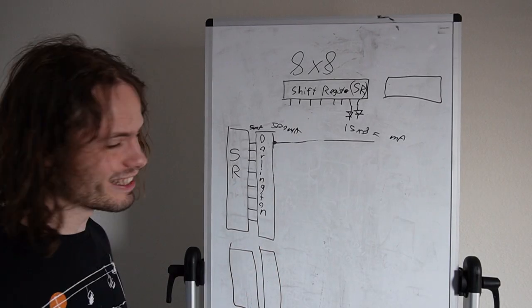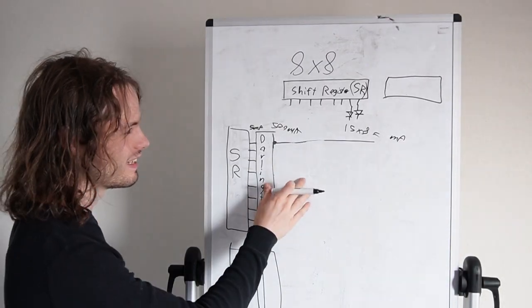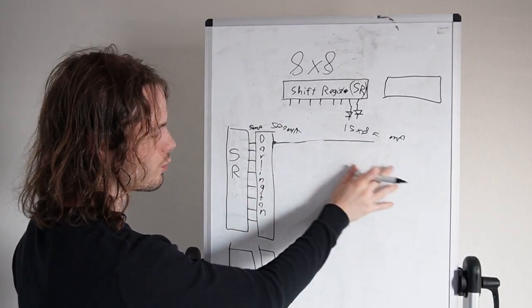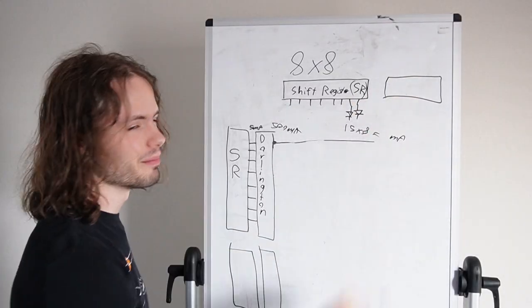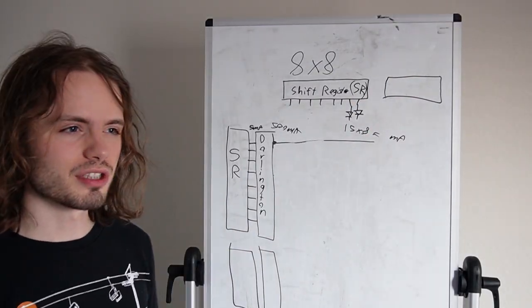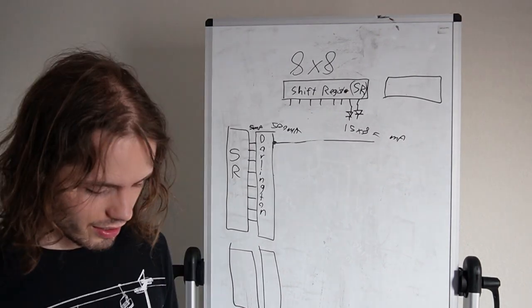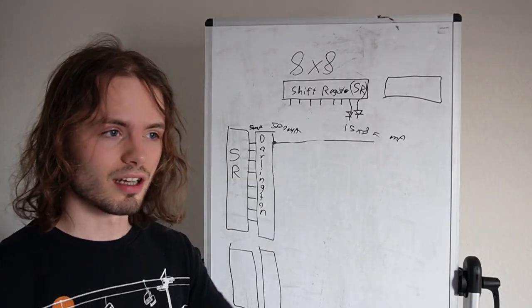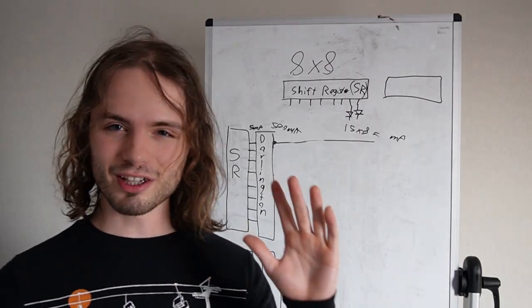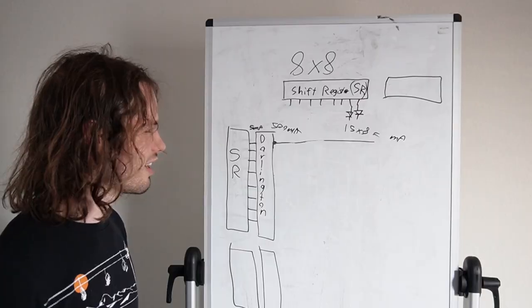The only issue is that once you start adding more columns, the Darlington here might not be able to handle the extra current, but that's for another point, and I think there's still a way to probably get around that. Maybe it's just another Darlington array or something where you put them in parallel, but anyways, I feel like I've talked enough on this, and that's the main gist.